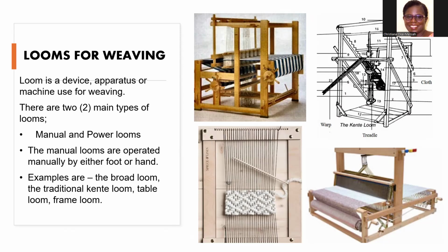Then the warping stage, we also learned about the crossing. The crossing determines the actual weaving. If you make any mistake in the crossing, all the yarns will entangle.